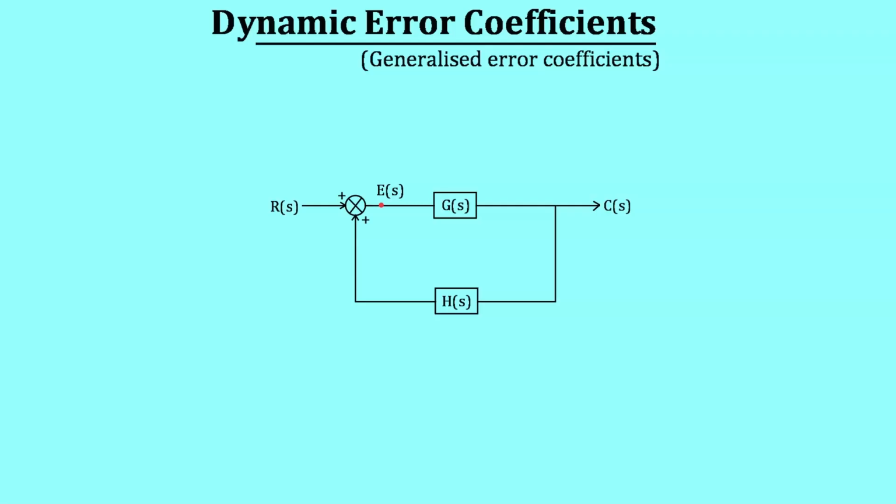One thing you might have seen, and will be seeing in future lectures also, is that most of the time I consider a negative feedback system. But what if in the exam the question is of a positive feedback system? Many times students get panicked for no reason at all. Even if a positive feedback system comes, simply introduce two negative signs: one sign at the comparator and the other sign at the feedback function. Because if you multiply two negative signs, it will eventually give us a positive sign. And the positive sign is converted into two negative signs so that our system again becomes a negative feedback system.